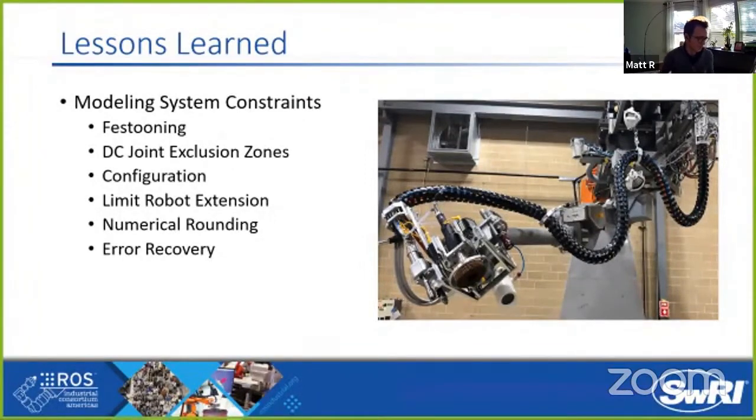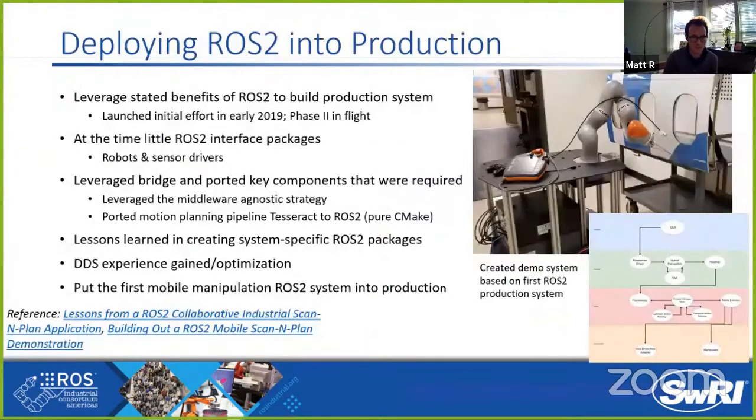This is a complex sort of motion planning scenario for when you're trying to carry a lot of payload on the end of a robot arm. It basically restricts the manipulator's free space. So we've been further refining and getting feedback from the user community at these deployed systems, and people are using the suite of tools around the systems to further refine how we can do the constraint modeling, enabling the tuning of the constraint modeling to then feed into the optimization-based motion planning. And so these are some further tools that have been made available, enhancements, and for instance, in this case, Tesseract, but these can easily be applied to other motion planning environments.